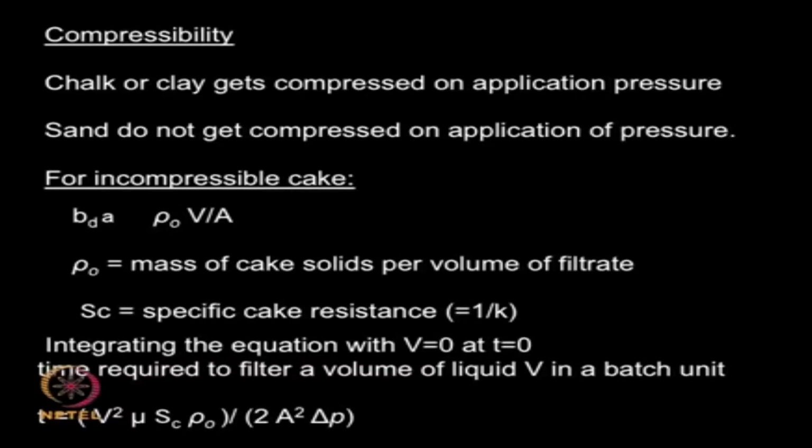And then number 3, we assume an average rate of filtration, that means we assume dV by dt is the average rate of liquid that is filtered over a period of time. So by assuming these 3 we end up with the relationship for the time of filtration to filter a slurry volume of V, and these are the